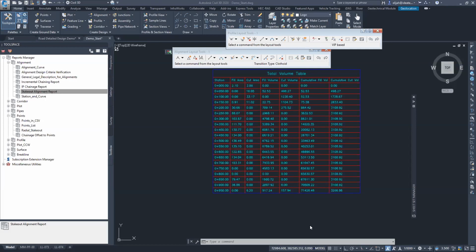He would also like to know, can we do pavement design as well using Civil 3D, or is it restricted to road alignment? So Civil 3D will only allow you to do what we call more of geometry. That is the vertical profile, horizontal profile, plus the various sections or assembly of the road. But pavement design is usually more of a specialized component of road design. So Civil 3D doesn't do it.